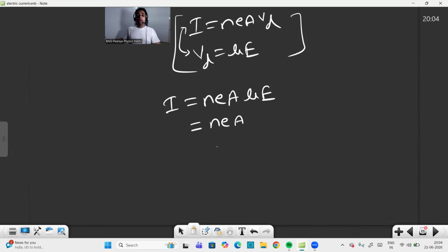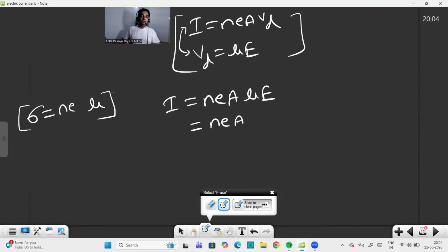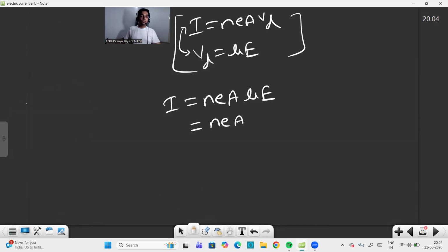Now what can we relate here? ne mu. Mu is what? Mobility. So now the relation between mobility and conductivity, what can I write? Conductivity, here a new term we will define, that is nothing but ne mu. So I will define the new term conductivity, and conductivity is ne mu.